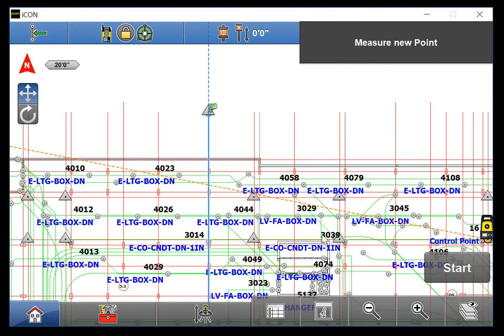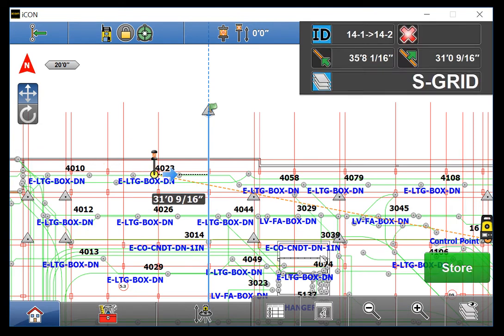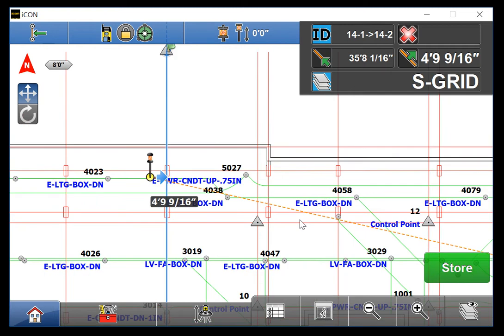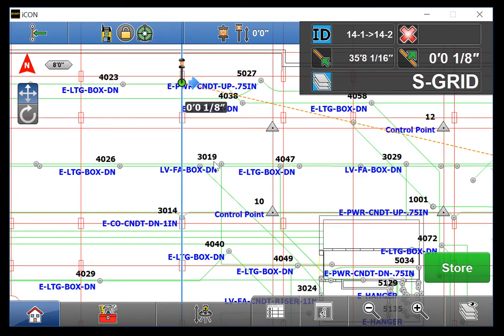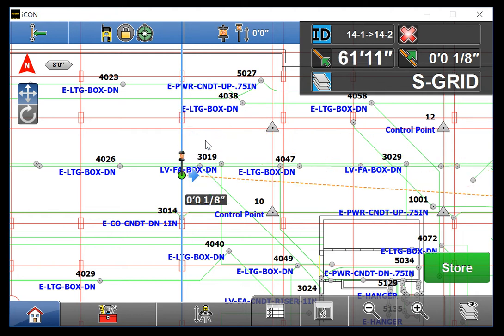Once the total station is locked on your prism, click Start. And the first thing you'll notice is your blue arrow pointing you towards the line and the distance you need to move in order to get on the center of that line. Once I'm on the line, I can make a mark, a crow's foot, or however you need to mark it. And then you could walk down, make another mark, and snap a chalk line on the deck or whatever surface you're working on.